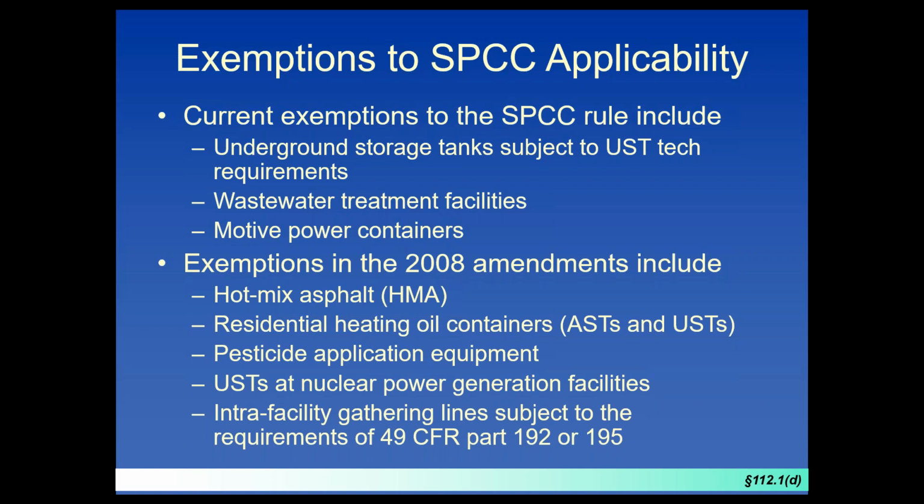However, if that wastewater treatment facility has, and will almost always have, backup power generators, and those generators are greater than 1320, those are SPCC regulated. So that is not a facility-wide exemption. And that's certainly important for you guys. Also important, motive power containers. So if you have a truck yard, and all it is trucks, you don't do any fueling, and there's only the containers that store fuel for the propulsion of the vehicle, those are out.